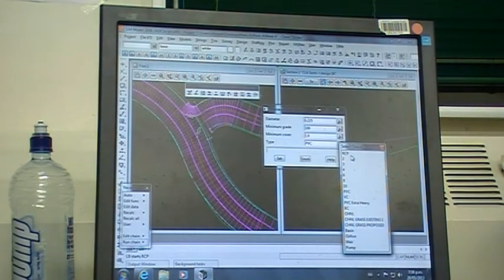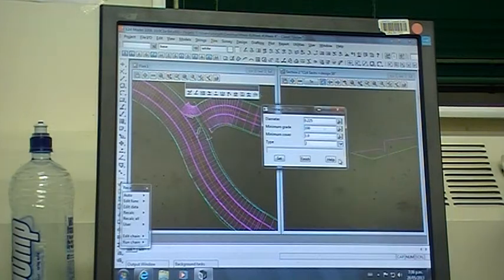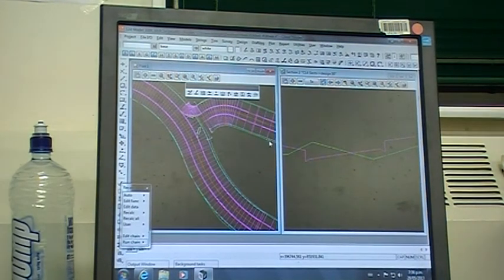Okay, so class 2 is a standard pipe. Class 4 is a stronger pipe that we use under roads. Again, we'll cover this. This is just a quick overview. So I'm going to pick a class 2 pipe. Set and finish. Okay, now I don't need to go and muck around with anything. Now when I start to design, it's going to instantly go for those defaults, and if they don't suit us, then we can change them later.